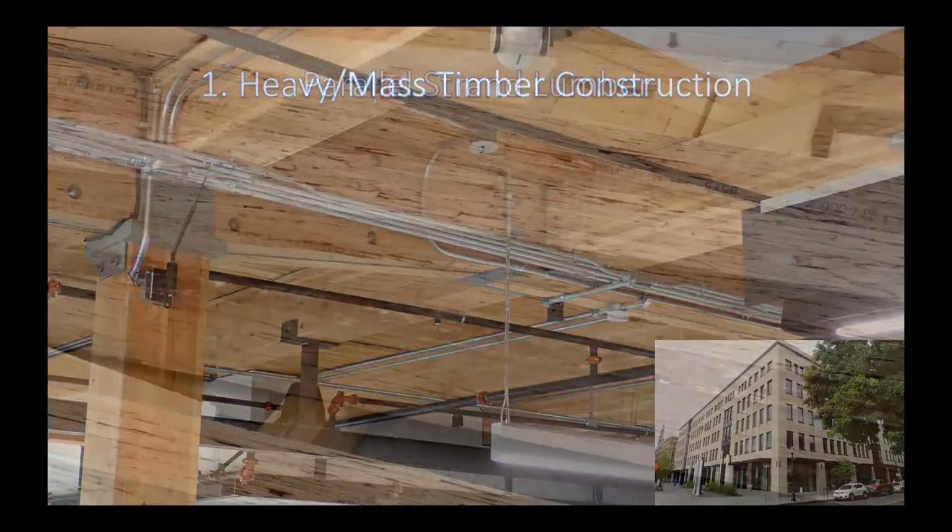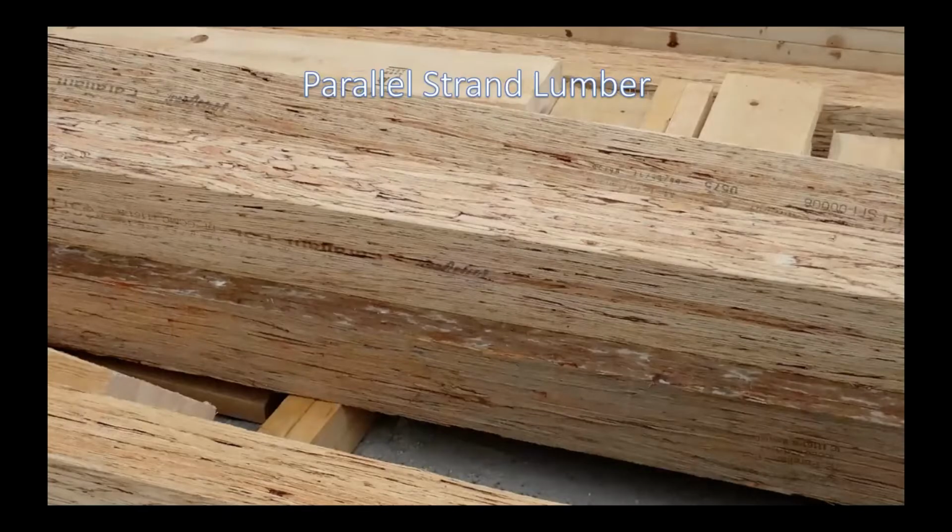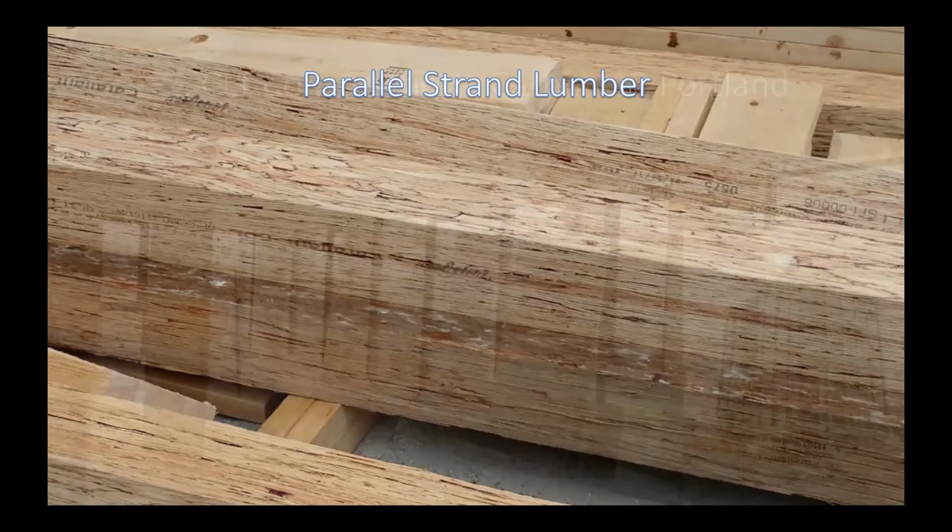But the material that they do have over there that we don't have here in terms of engineered wood products, that was of course glulam that we saw. Although we have got LVLs as well, something we don't have here is parallel strand lumber, and this is an immensely wonderful product that they have over there. It is harder than hardwood. It's a very, very strong, very, very rigid material, and they take advantage of this material over there, which would be nice if it were introduced in Australia.